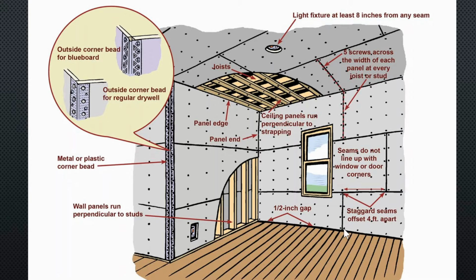An experienced carpenter, an experienced renovator will make sure that as he's building the wall, there's a piece of wood behind those seams for those screws to go into. And that's the thing that we're dealing with today when we're moving our joists just a little bit, to make sure that they are supported and that there's wood to screw into behind them.